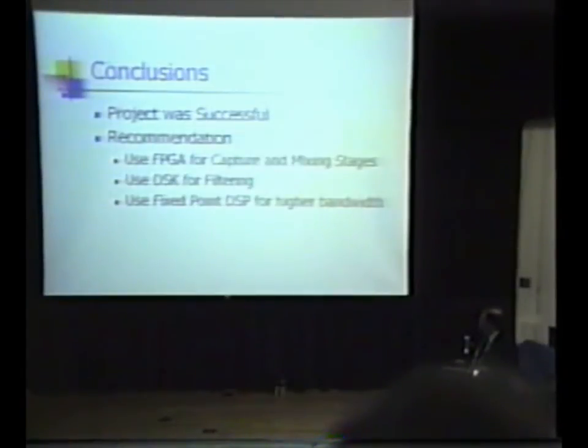Okay, conclusions. Project was successful. A couple recommendations are to use the FPGA for the capture and mixing stages and use the DSK for filtering. Another recommendation to increase speed is to use fixed point DSK from Texas Instruments for higher bandwidth.